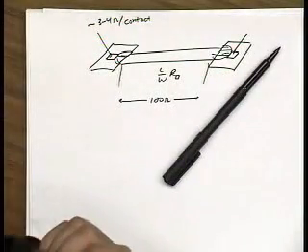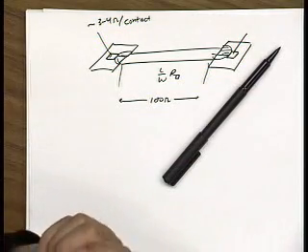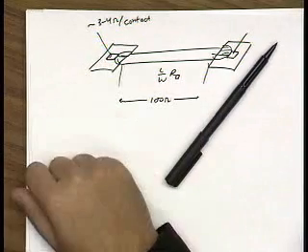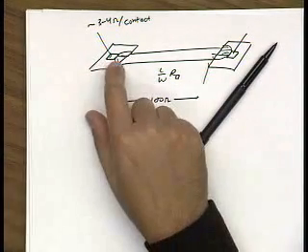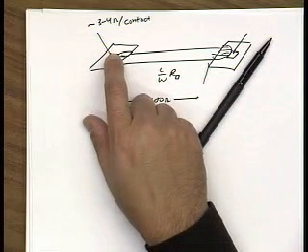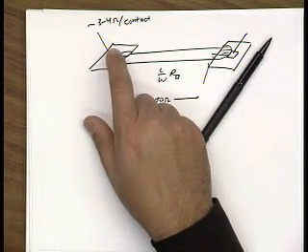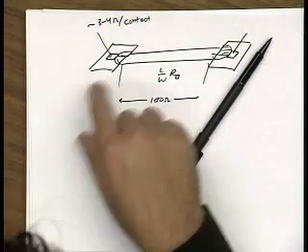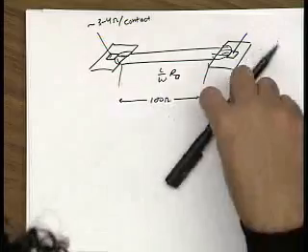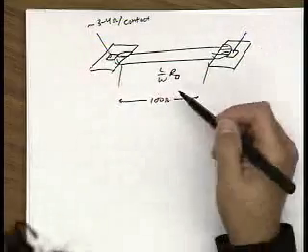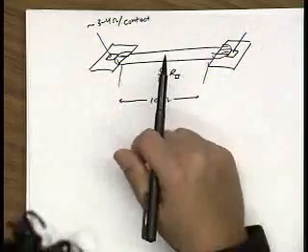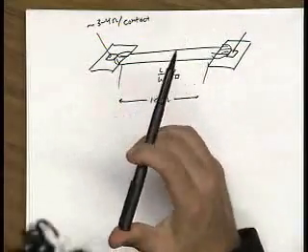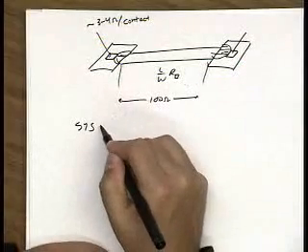If I really do need 100 ohms, then I shouldn't just use one contact. In fact, I should use a lot of contacts to minimize the contact resistance. It's always a bad idea to use just one contact because that's a good way for your chip to fail. It's very likely that that one contact may not work, and then your resistor's floating. So always use more than one contact. And if I do a good job and make sure that the layout is right, I can take the systematic error away for the most part, right? So that systematic error is not a big deal.